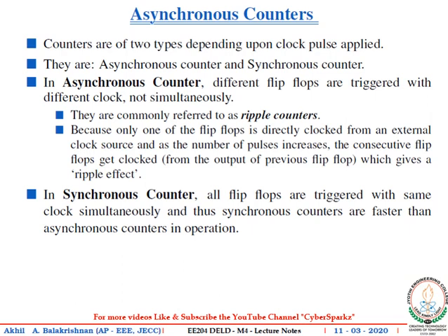A digital counter is a set of flip-flops whose states change in response to pulses applied at the input to the counter. The flip-flops are interconnected so that their combined state at any time is the binary equivalent of the total number of pulses that have occurred up to that time. Thus, a counter is used to count pulses.